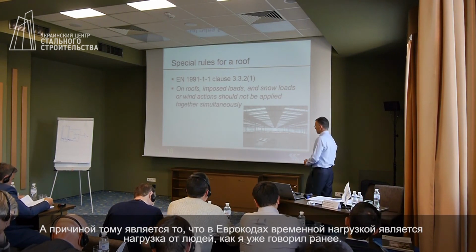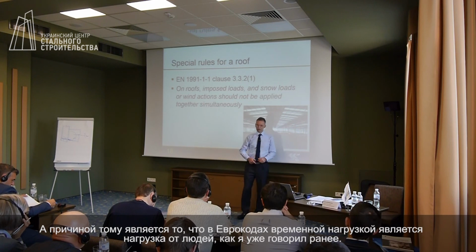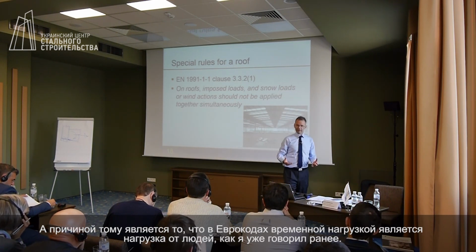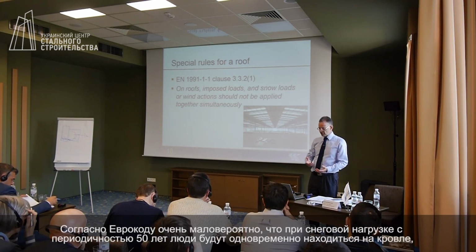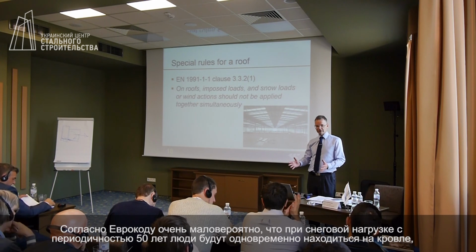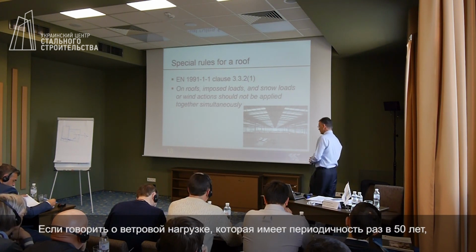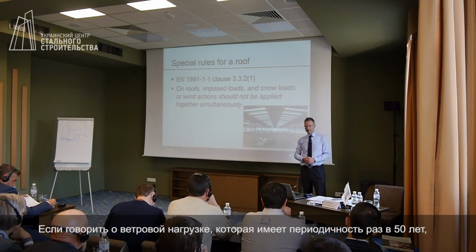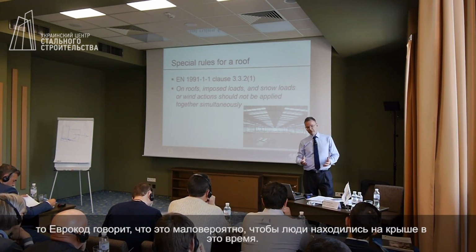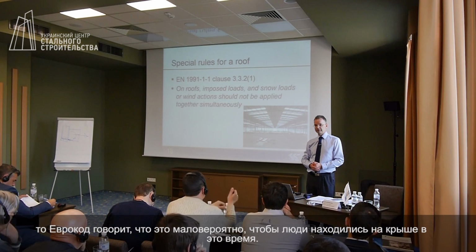And the reason for that is that in the Eurocode, the imposed loads are taken to be people, as I said earlier on. So if you have the 1 in 50 year snow load, would you have people on the roof at the same time? And the Eurocode says that's very unlikely, so you don't consider that possibility. If you've got the 1 in 50 year wind load, would you have people on the roof at the same time? And the Eurocode says that's very unlikely, so you don't consider that possibility.